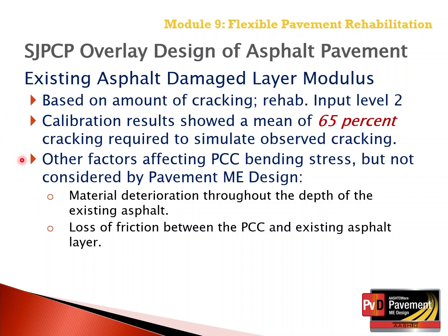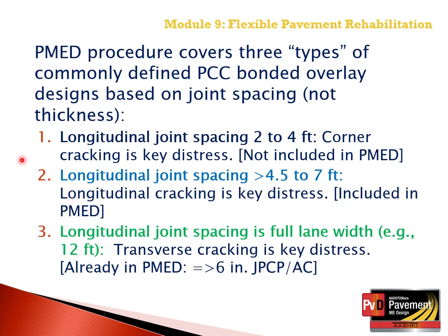Other factors affecting the concrete bending stress, but not considered by the Pavement ME design software, are material disintegration throughout the design life of the existing asphalt and/or loss of friction between the concrete and existing asphalt overlay. Those are not considered in the short jointed plain concrete pavement overlay design of asphalt pavement.